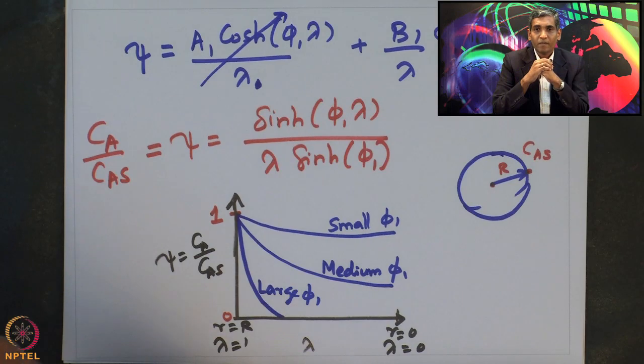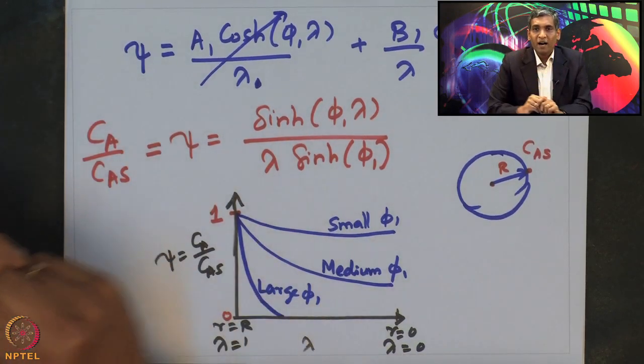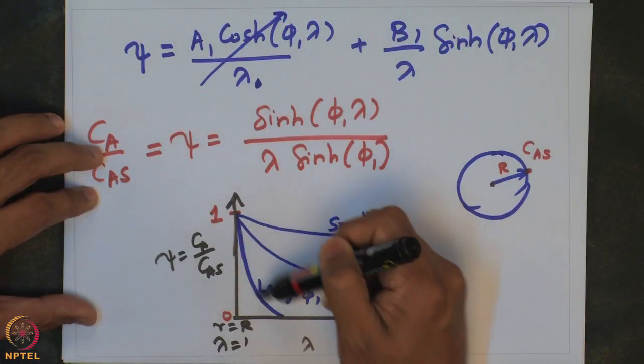The diffusion rate is very slow, so as soon as a small quantity of species diffuses in, and because the surface reaction is relatively rapid, the reaction happens immediately and the concentration drops to 0 close to the exterior surface. That is nicely captured by this curve.